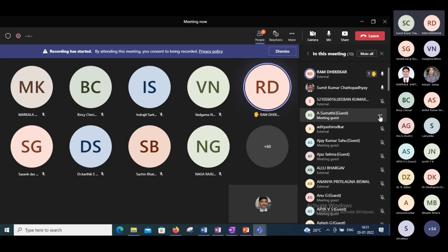Each are operating at 2.5 kV. So you do reduce voltage, so you do not need any series connection. And moreover, having multiple levels reduces the need for high frequency switching. That 5 kilohertz I was discussing will be coming below 500 hertz maybe.